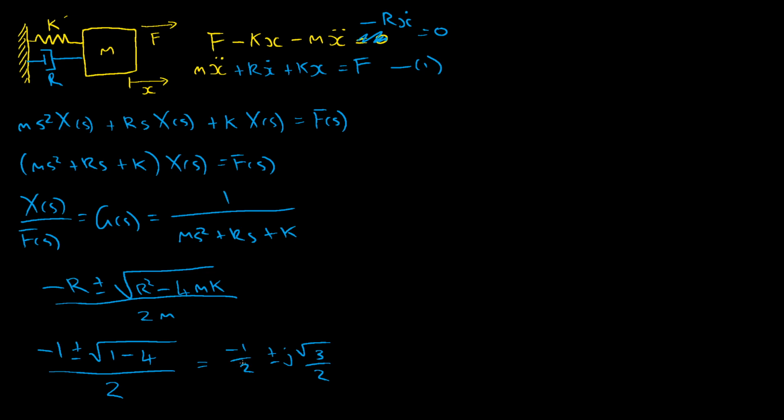In our last example, before we had the damping, our poles, or the eigenvalues, had 0 real component and were on the imaginary axis. This is what we would describe as a system being marginally stable. If these were slightly over into the right half of the complex plane, the system would be unstable. You could see this if you solved the time domain equation for this system: there would be terms that would grow unbounded. And here, you would expect to see a time domain response that oscillated forever. It didn't explode out and it didn't shrink down, it just went on forever. And that's why we call it marginally stable.